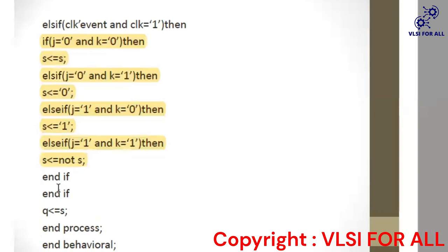After that, we will end the if statement 2 times, and at last we will transfer our result from S to the Q variable, and we will end the process statement and behavioral.